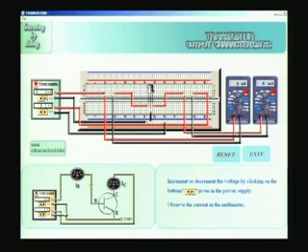Now, I am ready. I will now vary the VBB, the base voltage, in steps of 100 millivolts, and as I vary this, you can see the corresponding base current keeps increasing. Now, it is 4 microamperes for 400 millivolt. I increase to 500 millivolt, it goes to 5 microampere. So, if I keep on doing that for 1000 millivolt or 1 volt, you find it is about 10 microamperes in a typical case. This is reasonably a large voltage, even less than that you would get. Okay.